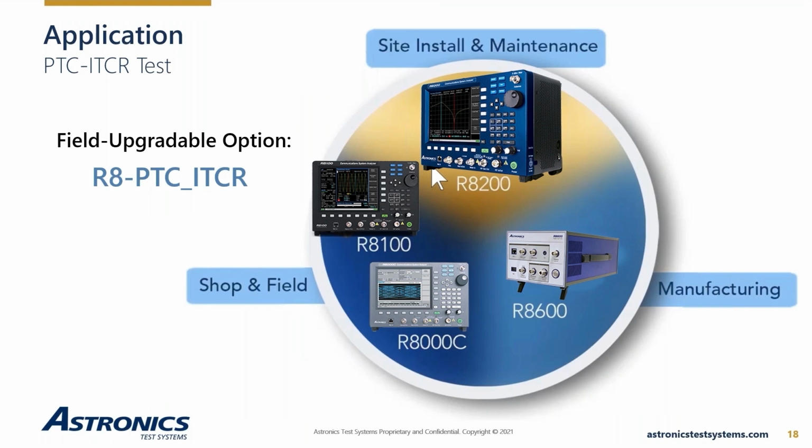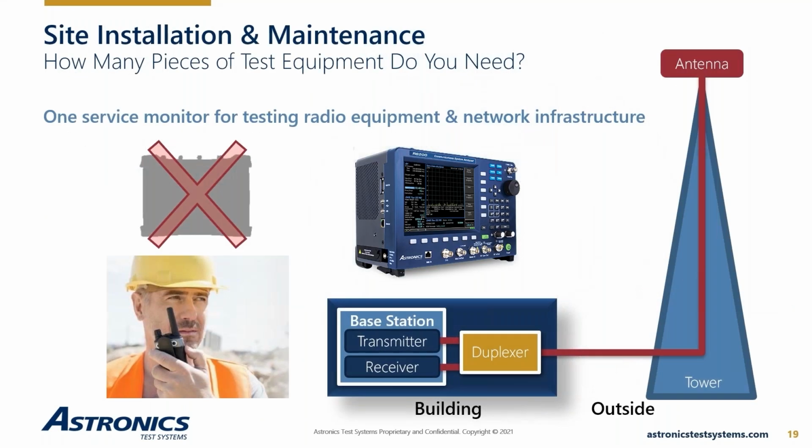And the fact that we've added this to the platform means, if I switch to the next slide here, that inside of a single instrument, you have all of the functionality you need for testing not only your radios and tuning your duplexers, but sweeping your antennas and your cables. All of that can be done now without additional equipment.